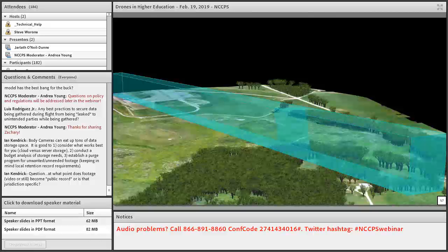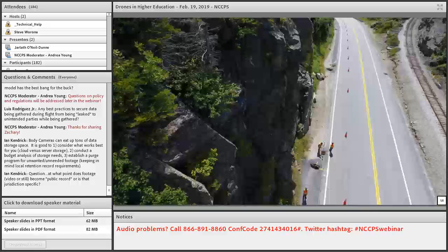So it's not just having information, but verifiable information that can be visualized. In other activities, we've used drones to assess rock slopes. So you can see a team here. They actually have marked off the road so that when we operate the drone, we don't get close to any incoming traffic. And you can also see a GPS crew out there gathering detailed ground control information.